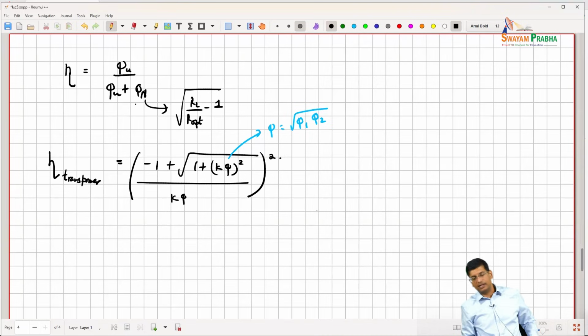So what this is basically saying is that in this case, in order to get good efficiency, right, you want to have a good kQ product, which basically means that if you are coupling with small k, then you need to use very good quality factor inductors, or if given a certain quality factor inductor, then you can get a certain insertion loss by picking a high enough k to build the system.